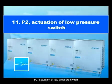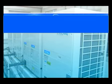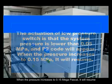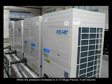P2. Actuation of low pressure switch. The actuation of low pressure switch is that the system pressure is lower than 0.05 megapascal, and P2 code will appear. When the pressure increases to 0.15 megapascal, it will resume.